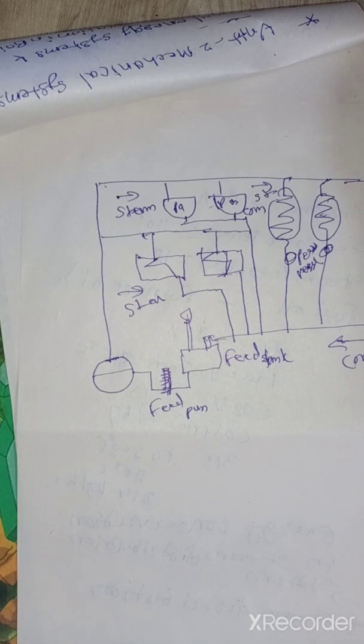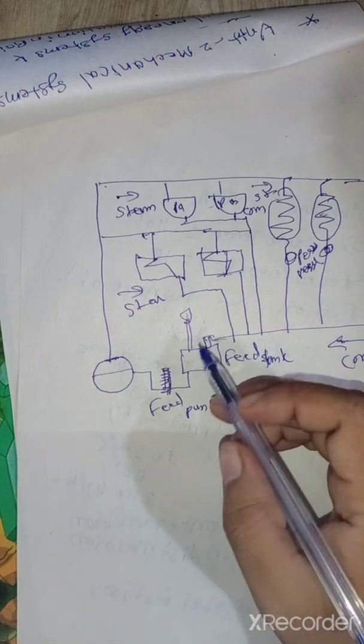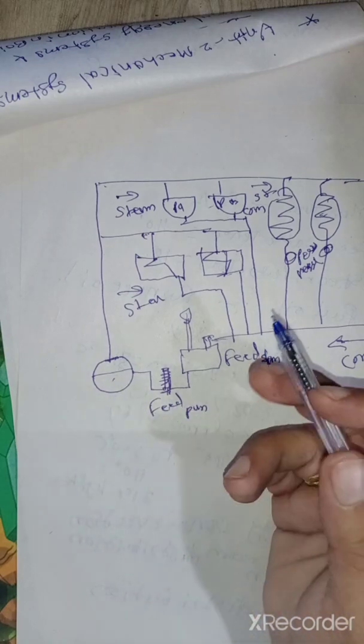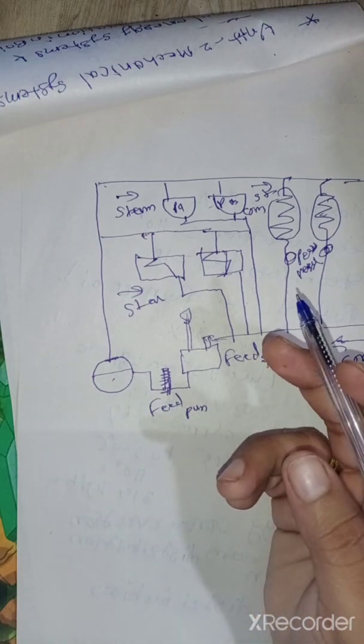As the steam condenses in the process, flow is induced in the supply pipe. Condensate has a very small volume compared to the steam, and this causes a pressure drop, right? This causes the steam to flow through the pipes.